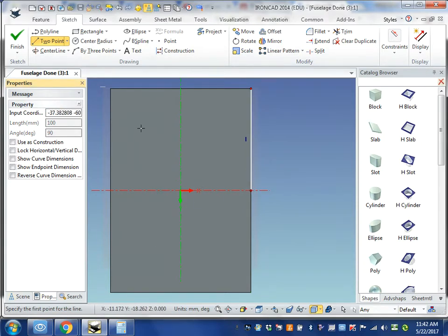Okay. Now I'm going to connect some dots here. For my swept forward design, I'm going to try to figure out, do I want to come, yeah, let's go from right here. I'm going to go from right here to right here. And I'm just doing 2-point lines. I'm left clicking. And I'm left clicking. And I'm not worried about the length because I'm clicking at this point and I'm clicking at this point. So because I'm clicking the endpoints, I'm not concerned with the length. I'm just letting our geometry determine that.